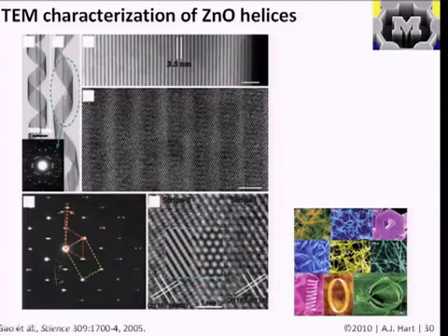And another thing you can do in the TEM is you can do electron diffraction, or you can take a diffraction image that lets you compute the crystal structure based on the position of the diffraction spots or diffraction peaks. And we'll talk more about that later, but in the TEM you can typically switch it into a diffraction mode and you take a picture, but this picture removes certain apertures and optics from the column, so you're able to just impinge the beam onto your sample and therefore collect a diffraction pattern like so.